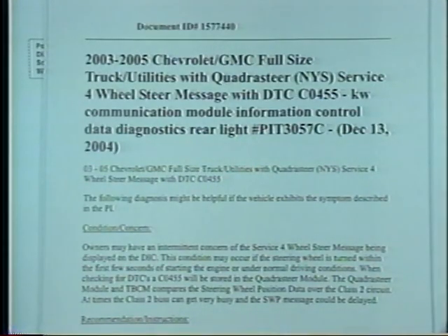All right? Now, if the customer cycles the ignition key, chances are, as long as they're not ripping on that wheel immediately again when they start it up, the vehicle will be fine. Okay? It just had to do with rotating the wheel too soon. And the fix for this is just to reflash the body control module. Use TID programming, reflash that BCM, and it should correct the condition.